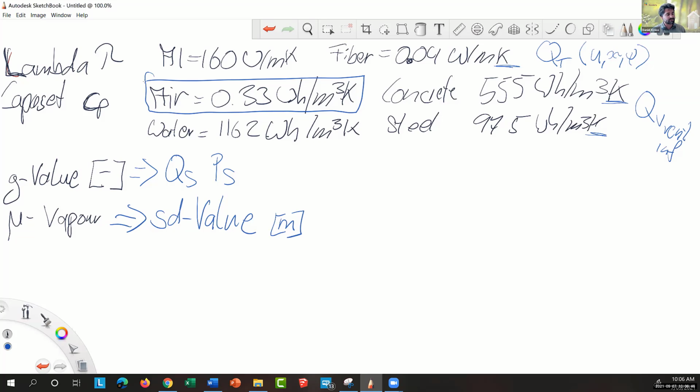The water system is different. The water system, we can switch it on, and then it takes a while until it actually comes to the radiator. And then when I switch off the radiator, it takes a while until all that heat of the radiator is actually coming out. This is the reason why our forward flow temperatures in a radiator need to be really, really low, just a little bit above what we want, so that we're not overcorrecting our temperature in the building.